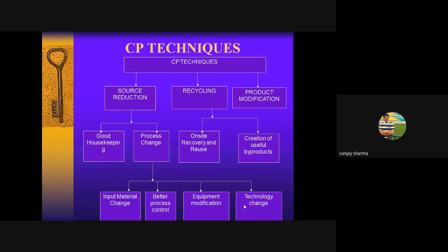Nowadays we are having this geopolymer concrete where we are not using cement as a binding material. We are using some other chemicals with the fly ash as a binding material, and you can develop concrete without cement with strength as high as, say, up to M100 also. And performance-wise, durability-wise, that particular concrete is much better as compared to cement-made concrete.